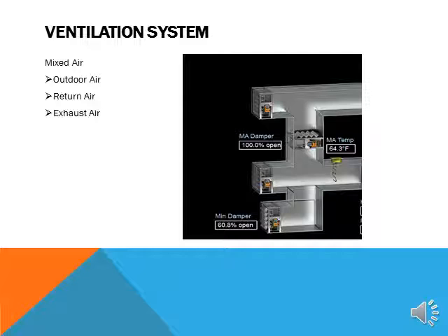The mixed air return air damper is the damper that allows the return air from the return air duct to return back to the supply side, or it closes off and pushes that air towards the exhaust damper, which expels it from the building, thereby working with the outside air damper to maintain the static set point in the building. These systems are popular in large buildings as well as economizer systems on small package unit rooftops.